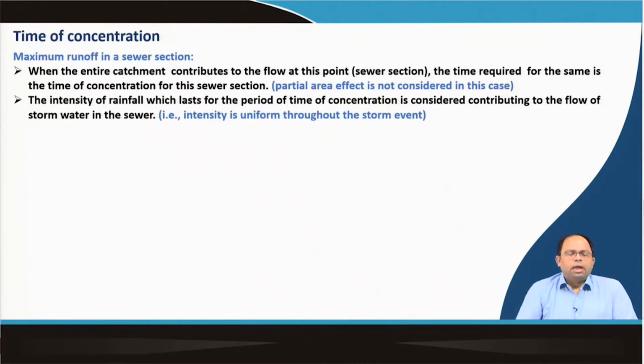So, now coming to time of concentration. This is basically used in determining the maximum runoff in a sewer section. So, we need to determine the sewer section based on whatever is the maximum runoff that it would carry in the course of its lifetime, right, in the course of its design period. So, when the entire catchment contributes to the flow for this particular sewer section or this particular inlet point, the time required for the same is the time of concentration for this sewer section.